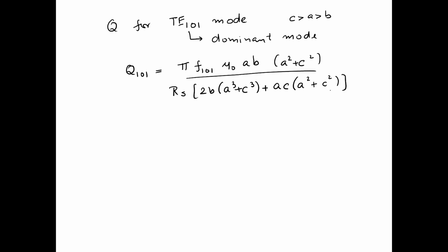The first question which arises is why do we choose the TE mode? Why do we like the TE mode? Remember when we were calculating the losses in the parallel plate waveguide, we had seen that the loss for the TM mode is going to be larger than the loss for the TE mode.